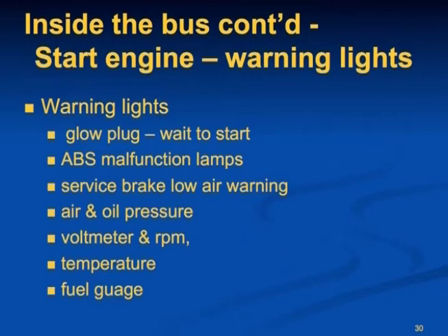A service brake warning light may come on during a hard braking application. It could indicate that at least one of the brake systems in a dual system is not operating properly. Do not continue driving the bus until it's checked by a mechanic.